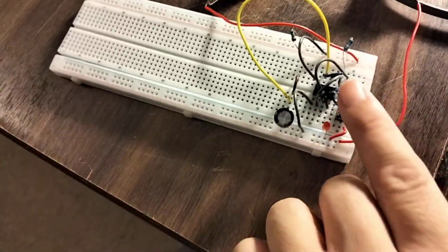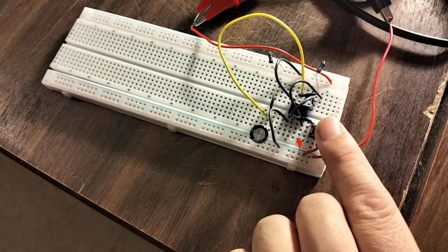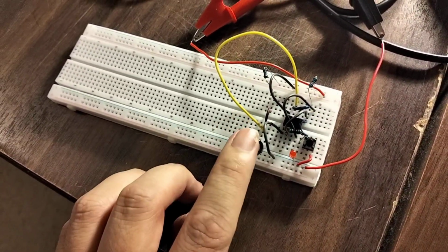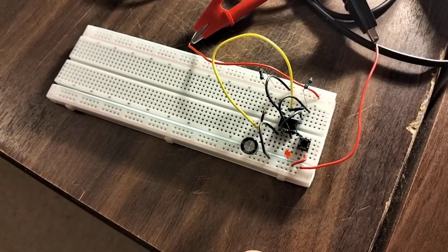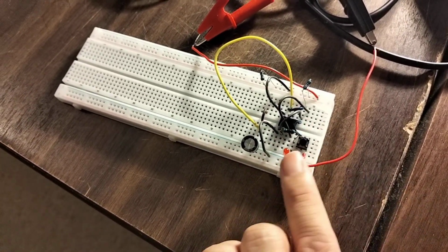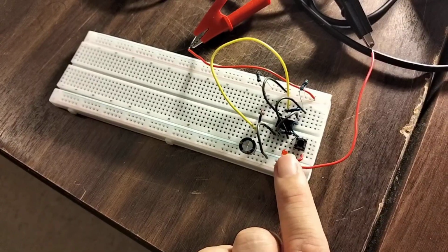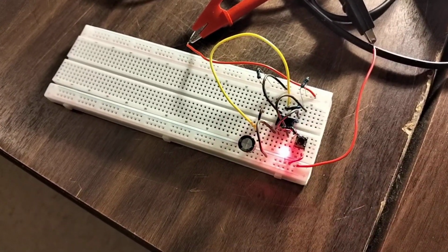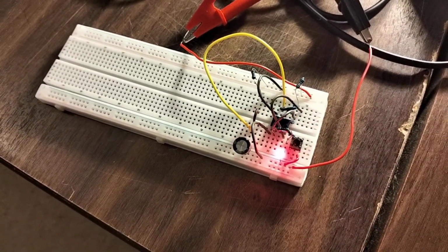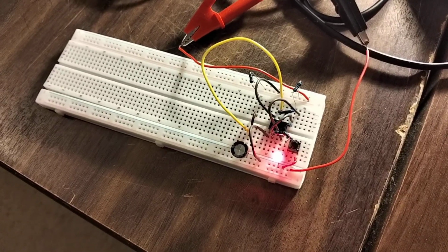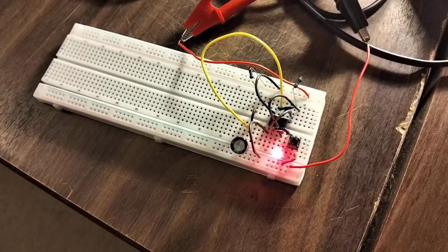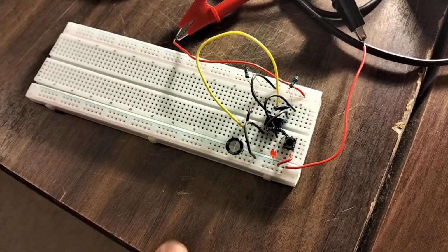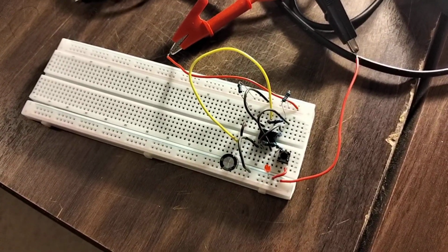So there you go. Once again, let's just show this one more time. It's a timer circuit. So basically, by changing this capacitor and the value of the resistor, because it's a series RC circuit, we can change the time it takes for this LED to stay on. So one click, and yeah, I've made it such that the two values approximately will take 10 seconds to turn off the light like this. All right, great.